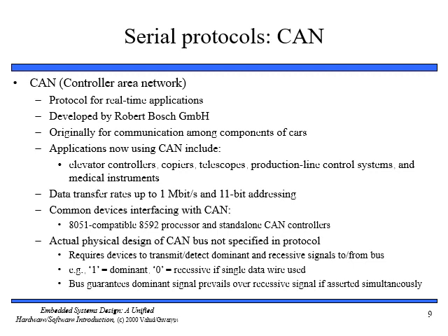Furthermore, the physical CAN bus must agree that if one of the two devices asserts a dominant signal and the other device simultaneously asserts a recessive signal, the dominant signal prevails. So in the end, I want to conclude, if some device asserts a recessive signal and some device asserts a dominant signal, the priority will be given to the dominant one. Okay, so that was about the serial protocol of CAN. Let's move on to the next slide.